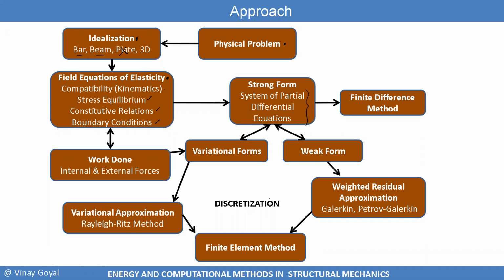Now, you could use the finite difference method as one way of solving the problem, but it doesn't lend itself very well for structural problems. And you'll see that in our area of expertise in structures, and also even heat transfer, the finite element method is a preferred approach. We use variational forms to develop these differential equations. And in today's lecture, now we're looking at the Rayleigh Ritz method as a way of solving these differential equations.